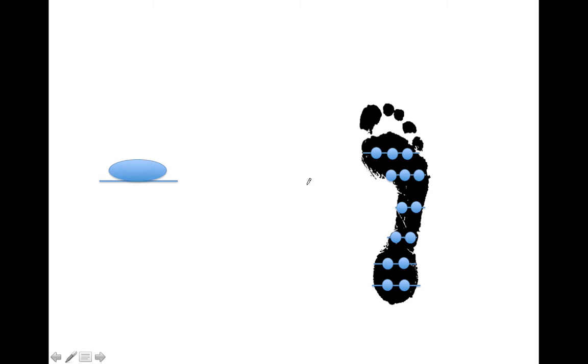But none of those made important use of a specific assumption, and it is for that reason that I decided to develop my own algorithm. It is not a very complicated one, but it makes use of the assumption that when a convex surface comes in contact with a flat surface, the pressure function it generates always has a form like that. And that's not to say that the peak is in the center, or certainly not to say anything about the slope of the function, but simply that it has only one peak.